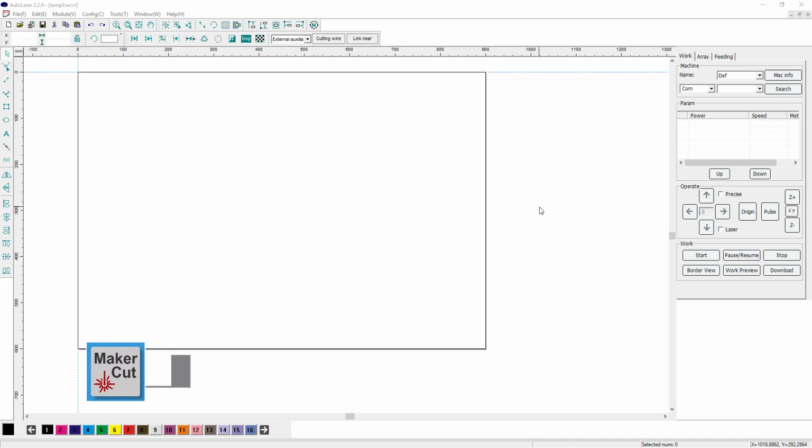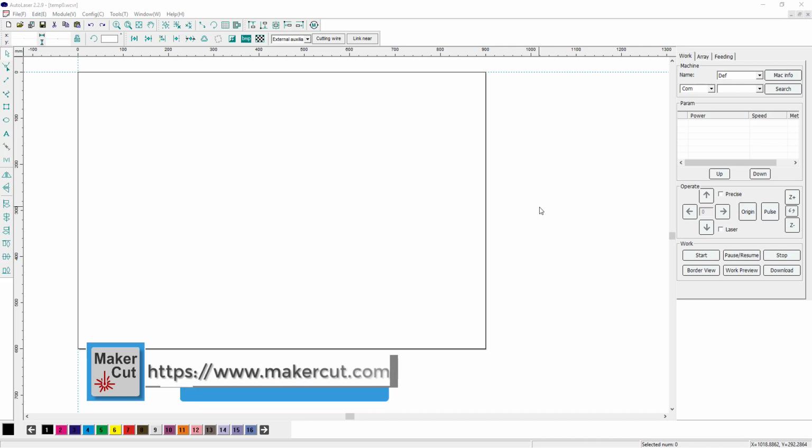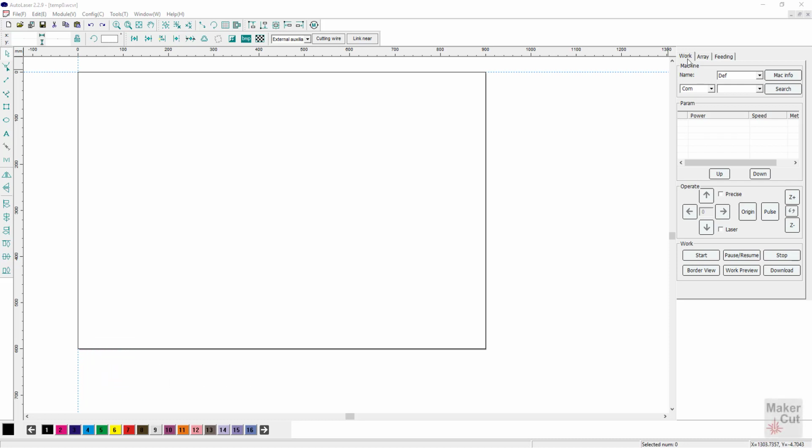We're going over parameters in Autolaser and how to configure your machine to use the Ethernet network and a TCP/IP connection. By default, Autolaser is set up to use a USB port or communications port. A lot of people know these as serial ports in the past. USB is a serial port. But serial ports can be unreliable when making communications, especially with large file sizes that are subject to interference from electronics. So what we're going to do is set up our machine to use TCP/IP.